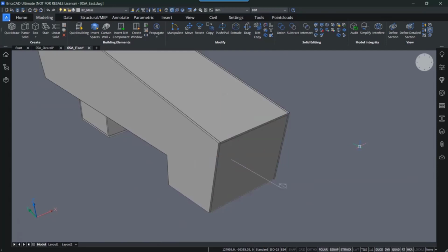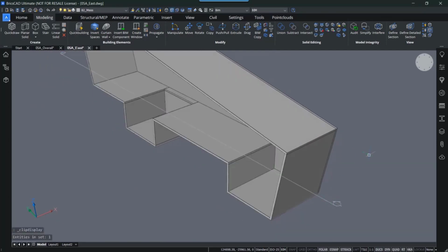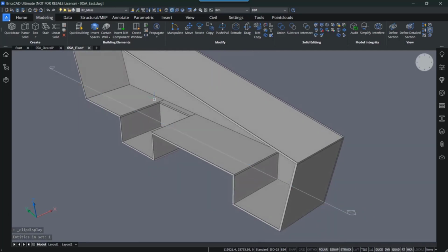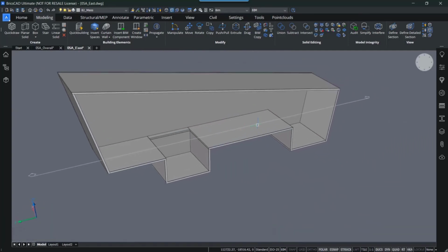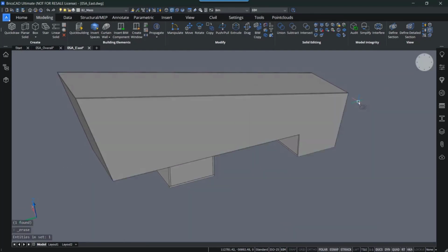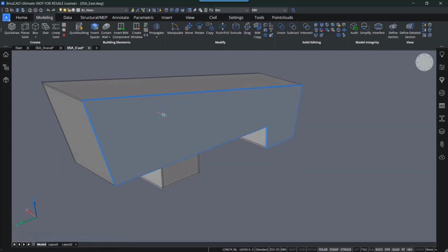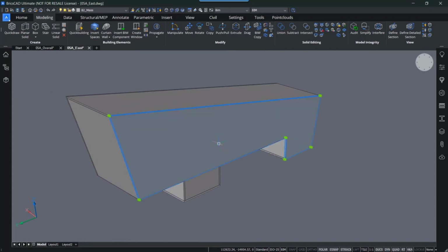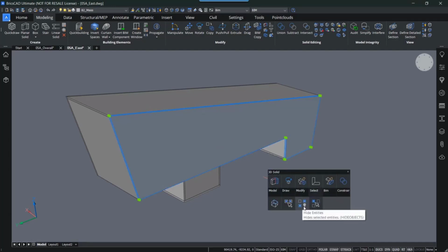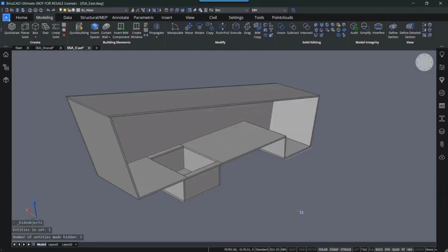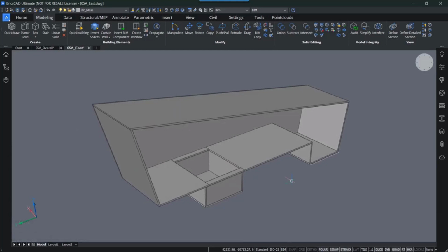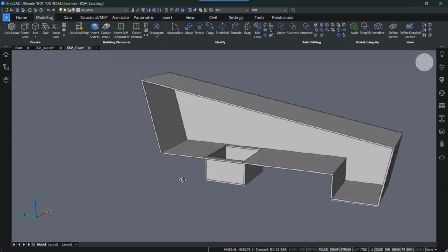Okay. Let me open back up, double clicking the section to open it up from the inside. Or what you can also do, let me just delete that for a moment. You can also select this, if I turn off the faces, so I can just select the solids. If I select this front facade right here, instead of delete, I can choose to hide it for a moment. So with BIM select and then hide entities, I can just make it disappear for a moment, and later on I can pull it back up. But now I can see how it looks from the inside.